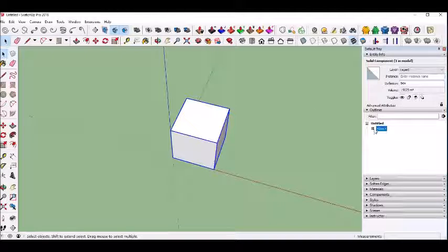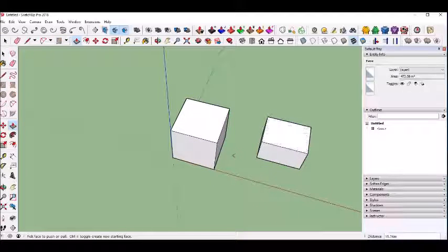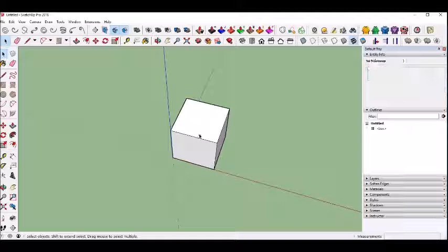And notice right here in our outliner we have a component that shows a box. Okay, it's named box. Now I'm actually going to do one more thing. I'm just going to make a random box right here, push pull up, triple click, and make group. Okay, notice in here it just says group. It didn't allow me to name it, and it's not a component. I prefer components. Why is that? Depends on the situation. Actually, I'll always use components.